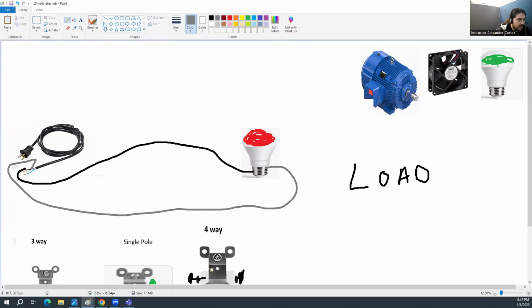It started from this power cord on this black wire, then goes to the light, the electrons go through the light, and with the neutral making contact to the neutral back on this power cord, electricity will flow. So we follow the electrons: they start here, go through the light, and with the neutral they connect, and you have a closed loop. Electricity will flow and the light will shine.